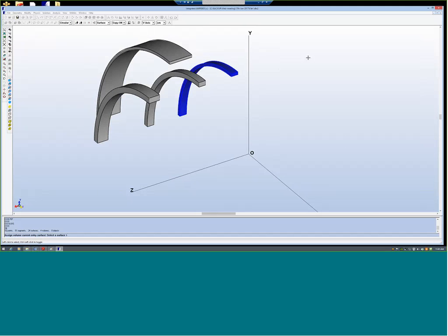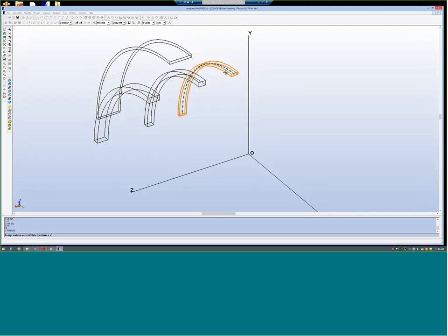Through this surface this current is entering, and now the program is asking to enter the total current or amp turns. So here we don't do turn by turn. Everything is through that cross section. We'll specify the amp turns. You can see here now that is the current.